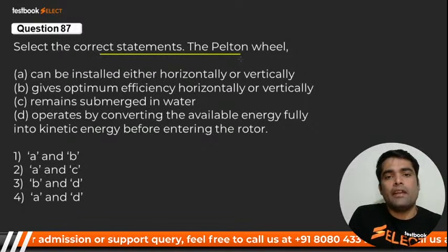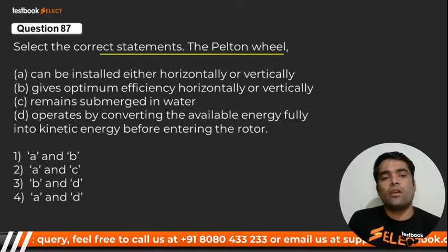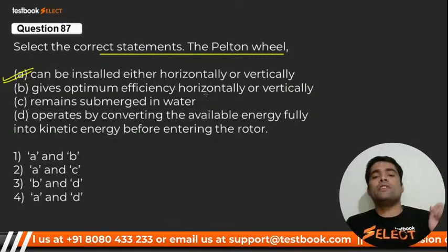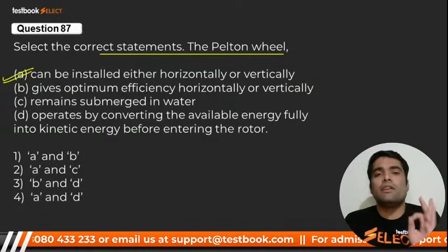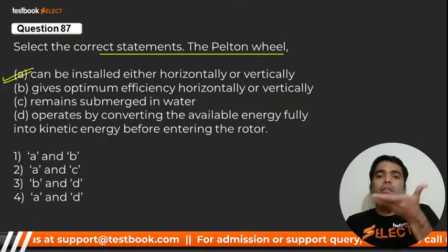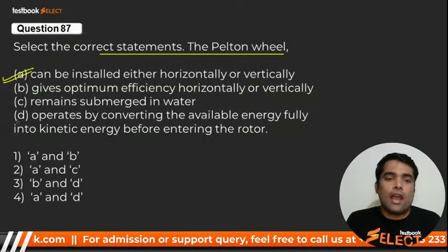Select the correct statement. The Pelton wheel can be installed either horizontally or vertically. It's correct. Gives optimum efficiency. No. Optimum efficiency is given by Kaplan. Right. Remains submerged in water. No. It is just above the water. Operates by converting available energy fully into kinetic energy.